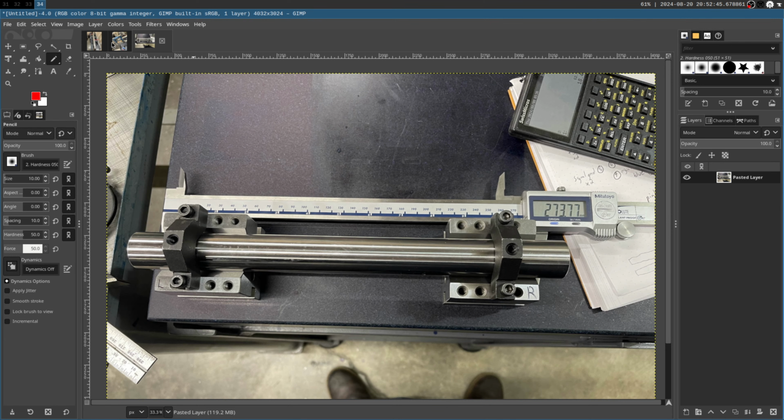But no, you don't have to compensate for that because your measurements include those bends, right? You can't scrape it into the unbent thing because your measurements include the bend, right? Because you have to put the headstock on to get that measurement.